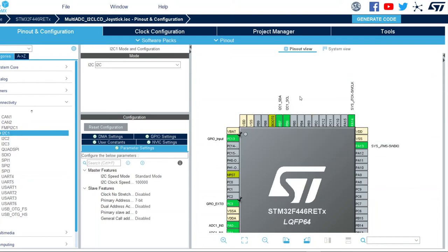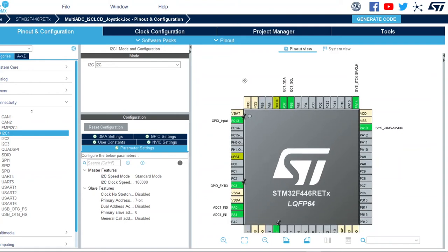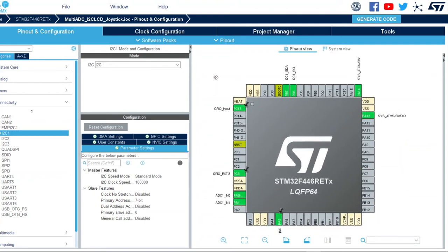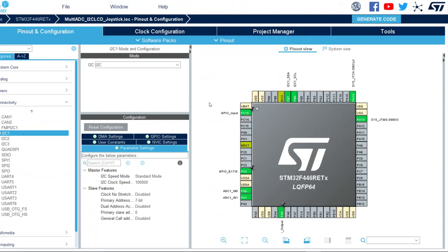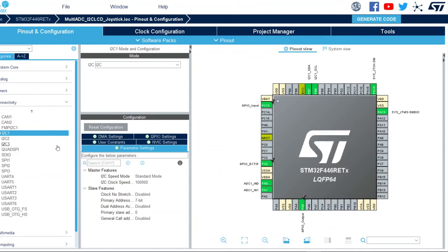So we'll be connecting the SDA and SCL of our I2C backpack module on the LCD to these pins. Basically we want to connect it to this I2C bus for the I2C communication, and that's it for the I2C setup. The STM32CubeMX really does make configuring or setting up easy, so we have to thank that one. And that's it for the I2C.